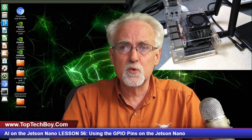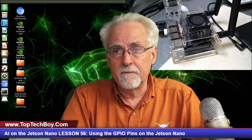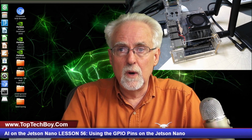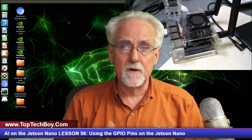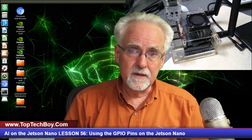Now, the second disappointment that I had in the GPIO pins on the Jetson Nano is they're 3.3 volts. The GPIO pins on the Arduino are 5 volts, and so that means if we've bought components along the way, interesting accessories for our Arduinos, those probably are designed to work at 5 volts, and they're not going to work on 3.3 volts. So by going to 3.3 volts for those GPIO pins, a lot of the gear that we have in our little supply cabinets are not going to work with the Jetson Nano.